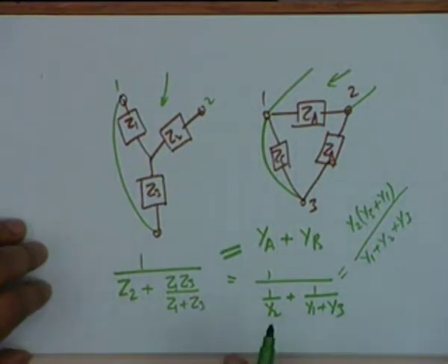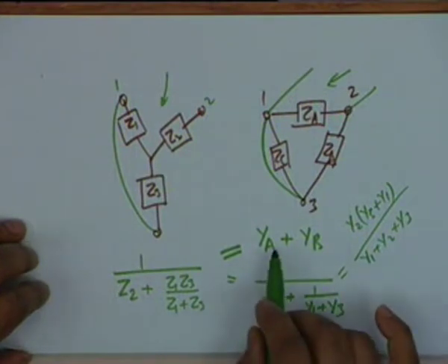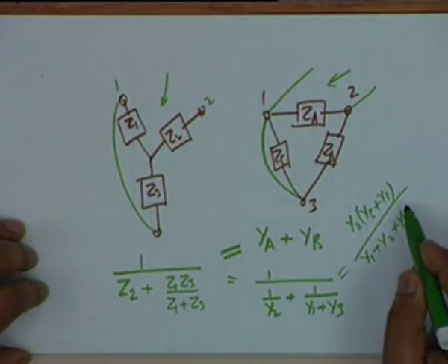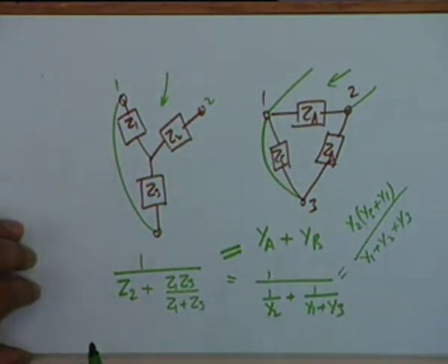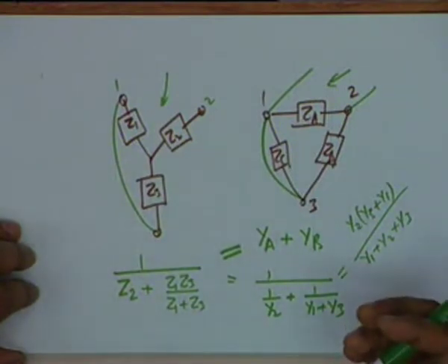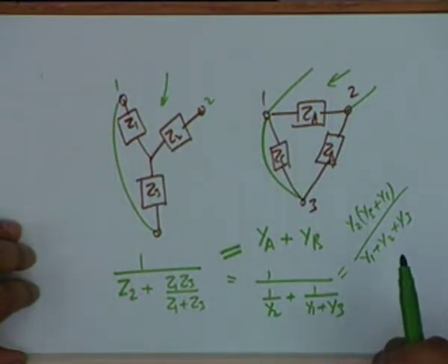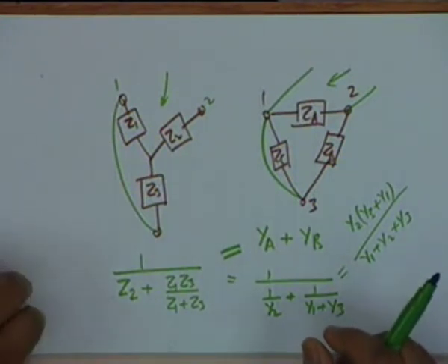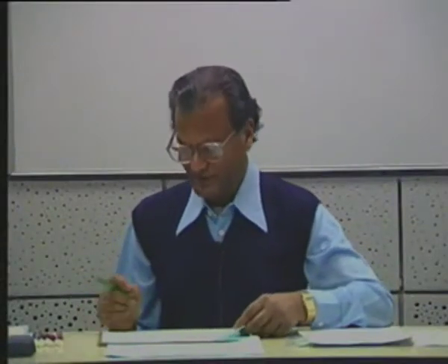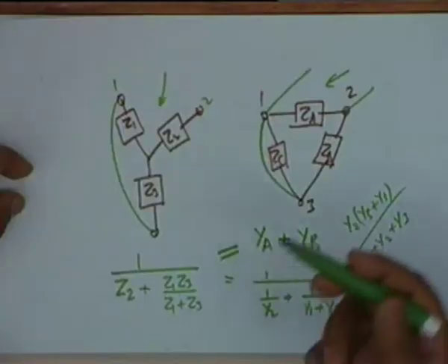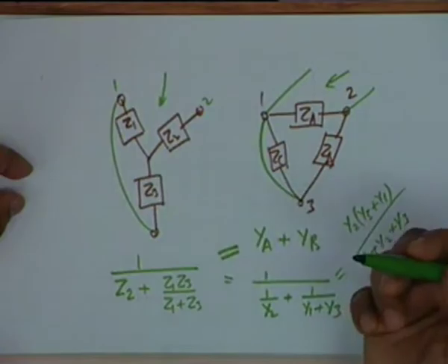Now what I have done is I have expressed the sum of admittances in terms of the admittances of the T network, and I can now write YB plus YC, another equation, YC plus YA, a third equation, and then eliminate one by one to find out the values of YA, YB and YC. From symmetry, the end results, do I have to explain further? I have to obtain 3 equations. One I have shown how to obtain, you obtain the other 2, then you make systematic eliminations.